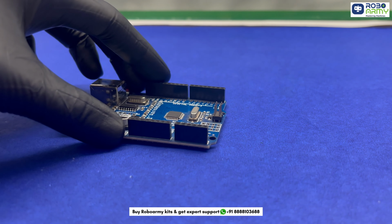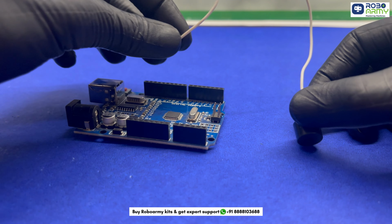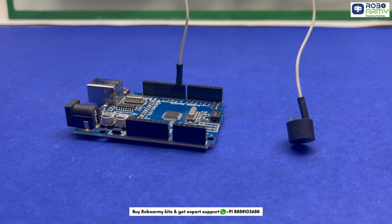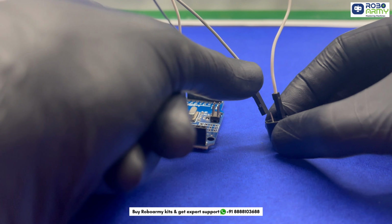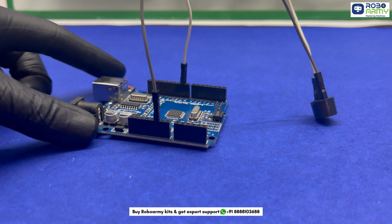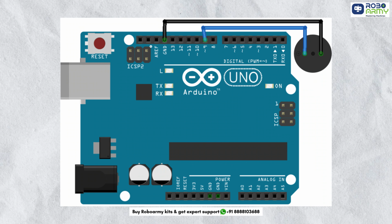The wiring is super simple. Take two male to female jumper wires. Just connect the longer pin of the buzzer, that is the positive pin, to pin 9 of the Arduino. Connect its shorter pin, that is the negative pin, to the GND of the Arduino. Make sure to double check your connections with the circuit diagram.